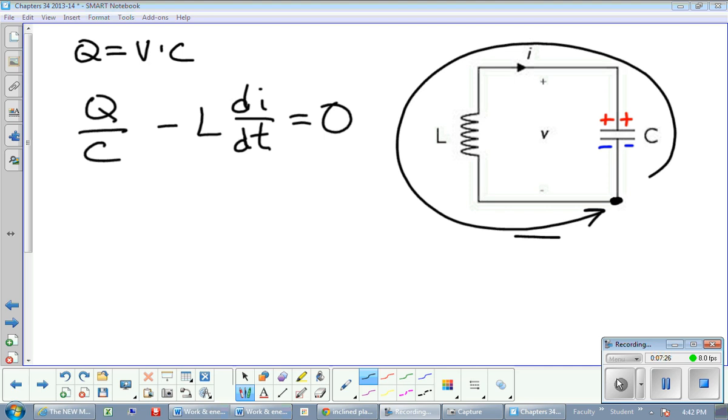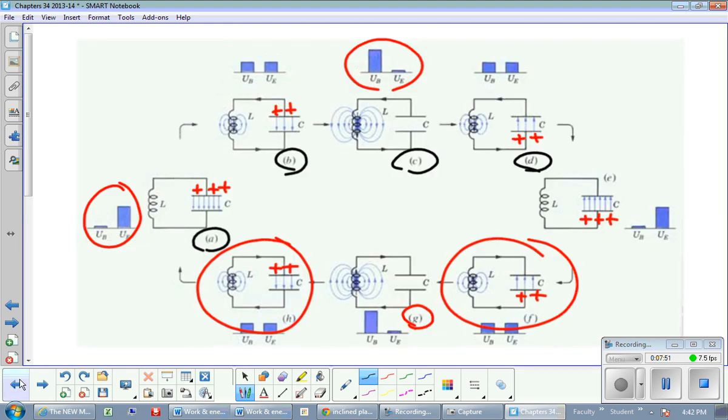And so you might think here, okay, good, I've got myself a formula, I can plug and chug the numbers in there and solve for whatever letter they want me to solve for, but don't be so hasty. This is not just your run-of-the-mill algebra equation, this is indeed a differential equation. And the way you recognize that is to see that the amount of current flowing through the circuit depends on how much charge is on the capacitor. And just looking back here, I think you can see that. When the capacitor was completely discharged, here in figures C and G, is when we had the most current through there. And likewise, when the least current was flowing, is when we had the most charge on the capacitor.